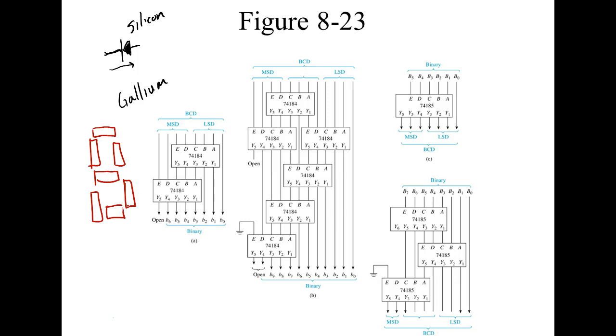But now what can we do? Well, I can turn this guy on, this guy on, this guy on, this guy on, this guy on. And what would you see? You'd see the number 3. So now we can display numbers. And these guys are still used a lot out there, the 7-segment LED. So this is a big one. This is using multiple LEDs to do this.